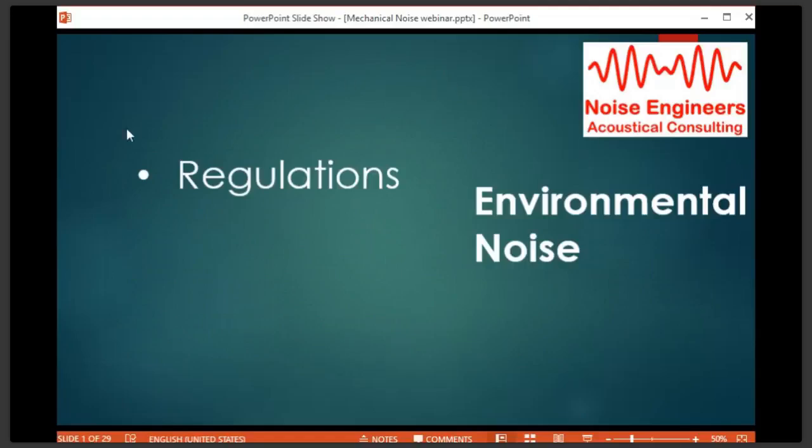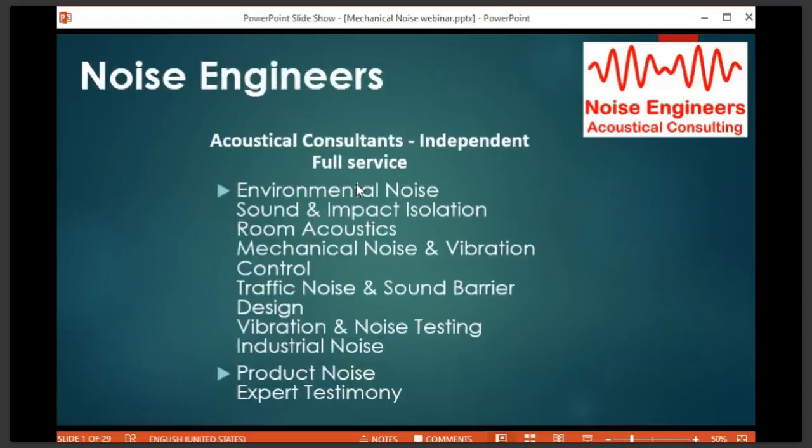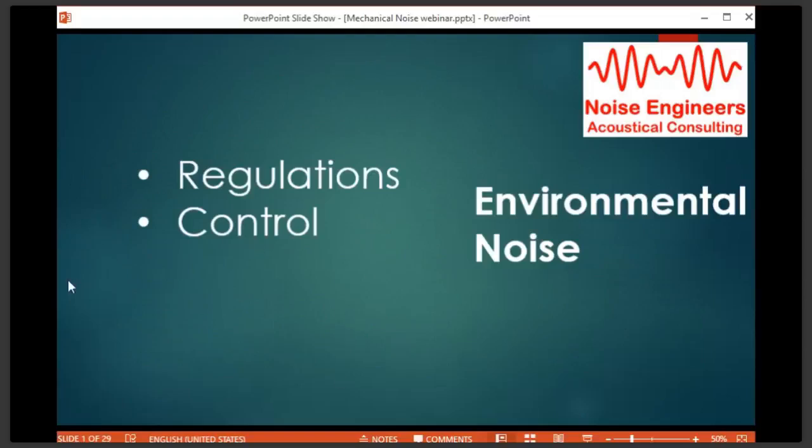So you look at the regulations, see how well defined they are, and then put in barriers, adjust equipment location and orientation, or add ductwork silencing, either on intakes or exhausts if needed. There's a number of controls that can be done. A lot of times it comes down to barriers because you don't want to affect the airflow, and a barrier can be very effective, depending on how much noise reduction is required. We have had orientation be the difference: just face a different direction, or move it to a different part of the roof if possible.